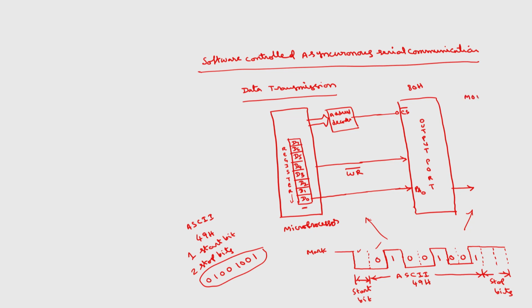First I will take MOV AL, 80H, because this 80H will be a control word for making all the ports output ports in mode 0. But this is also 80H, so to avoid the confusion, I will take this as F0H. F0H is the port address of port A. Then F3H will be control word register. So, OUT F3H, AL. This will program all the ports as output ports, but of course, we are using only one port.